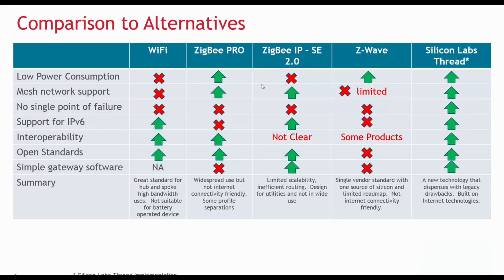This resulted in a stack that was lightweight from the perspective of designers used to complex and powerful Wi-Fi enabled systems like laptops, smartphones, and some of the more sophisticated electric meters, but too cumbersome from a resource point of view when it came to memory, bandwidth utilization, and power consumption on an embedded device. As such, this stack has yet to gain wide acceptance among utility companies and device manufacturers currently leveraging ZigBee Pro and SE1.x. It lacks the efficiency and scalability of ZigBee Pro or Thread, and its target market is admittedly the smart grid rather than the smart home.